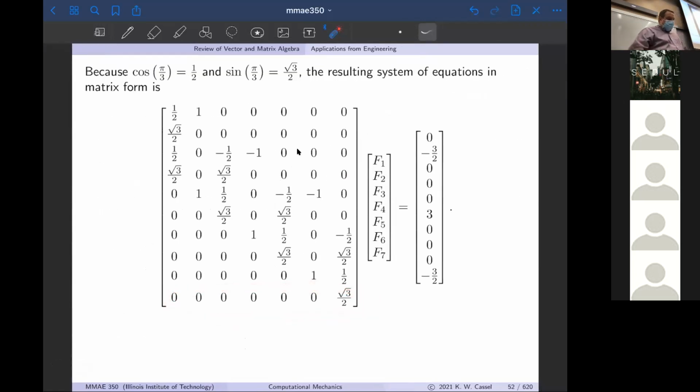This last equation, I can write as some linear combination. So something times one of the equations plus something times one of the other equations. And therefore, it's not contributing anything new to the information contained within the system of equations. It's redundant. So 3 of the equations have to be redundant in that way. If that's true, then I have 7 unknowns and really only 7 unique equations, and therefore I get a unique solution. That's what happens in these truss problems.